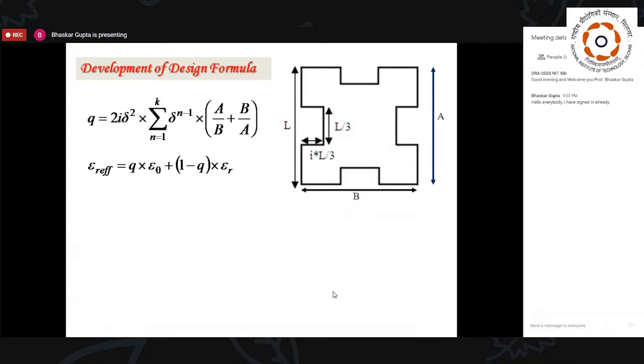See, if we now calculate this factor Q, like the filling factor of microstrip, then the effective dielectric constant, you obviously know the concept, so that everything like fringing and inhomogeneous nature is taken into account, so that the structure can be considered as effectively a homogeneous one supporting almost TEM modes.